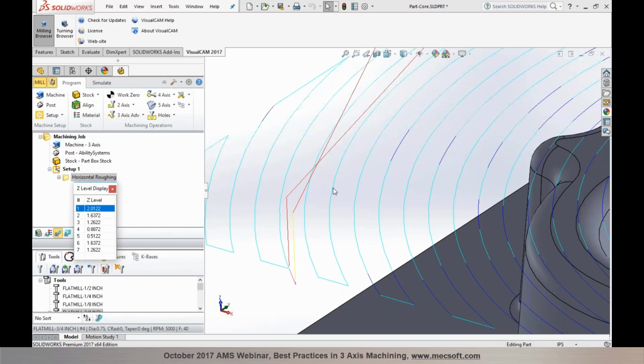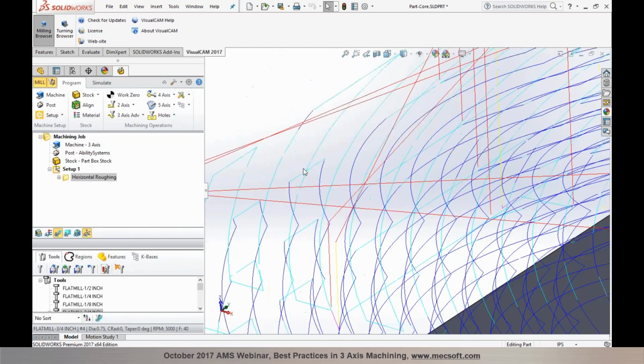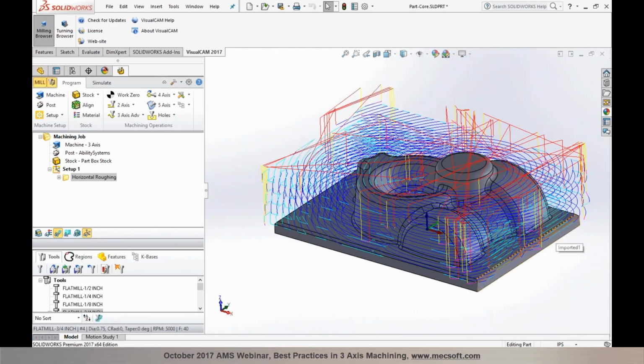The in tol and out tol settings allow you to control how much you can cut into the net shape. The in tol represents the maximum thickness of material that can be removed from your stock layer. You can control these parameters for each of these operation settings, and these settings are available in roughing and finishing operations in each of the 3-axis operations that you're looking to program.